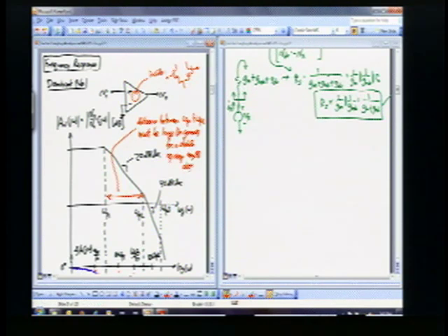Okay, so what does that tell us? That tells us that we can define omega P1 as a dominant pole. Okay, because that means omega P1 is going to be much less than omega P2 for stability. And anytime a pole is much less than any other pole in the system, we will identify it as a dominant pole. Okay, so omega P1 becomes what we'll call the dominant pole.